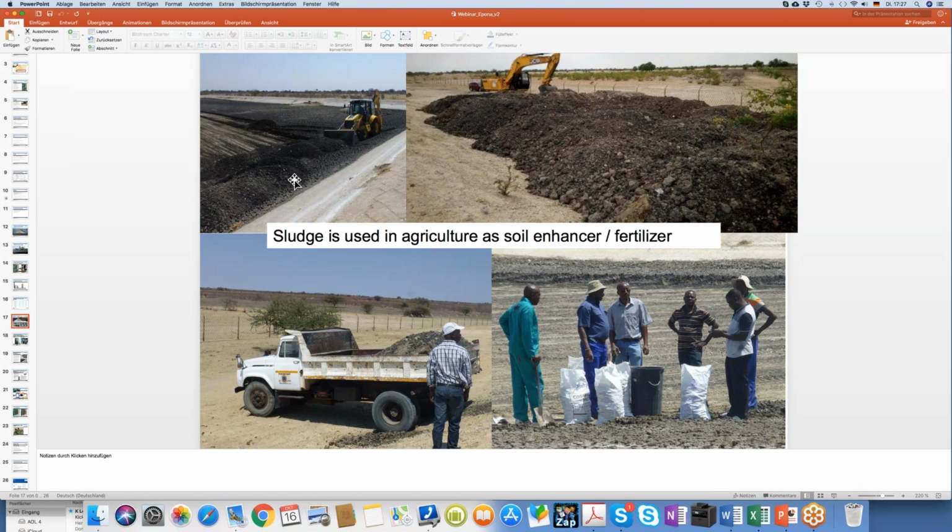Yes, I mean, we just discussed that if you look at what you see on your screen, these huge amounts of sludge, and the long time it takes to dry the pond and to desludge it. So maybe the idea of pre-treatment is easier than post-treatment, because then still you have to desludge the ponds, and we have seen that the ponds don't work very well.